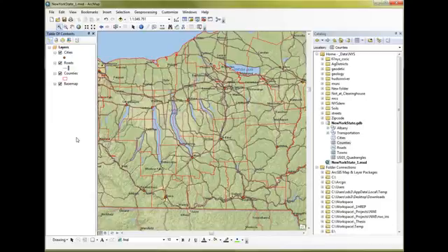Now the reason it did that is because ArcMap, if you've been noticing, draws from the bottom up. It lays down that base map, it then draws the counties, it then draws the roads, and it then drew the cities on top. And that's because things like base map, that's an image. It's solid. It's going to block out anything underneath it. Counties is a polygon. Now polygons can be filled or they can be hollow.